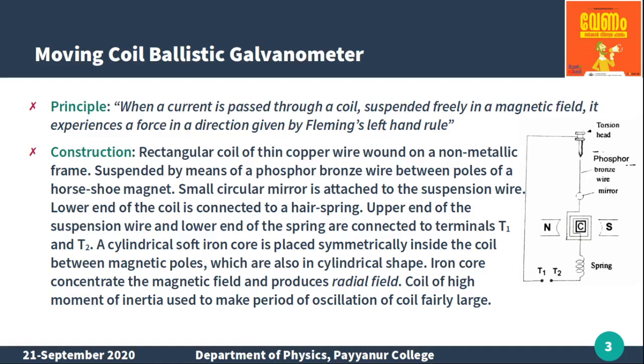Normal is important. That is the normal to the surface of the coil. So the surface of the coil will always be parallel to the field that is produced. That means the field will always make a 90 degree angle with the normal to the surface of that coil. That's the important thing that is used when we are deriving our equations.